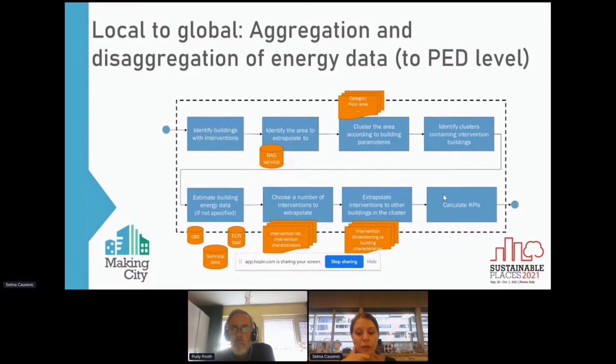similar buildings? And using different parameters, basically, we can say that for a specific building category with specific parameters, with a PV rooftop area of a certain potential, we can find a similar building, and using statistical extrapolation, we can see what would be the specifications or energy balance for a similar type of building. And then finally calculate the KPIs.